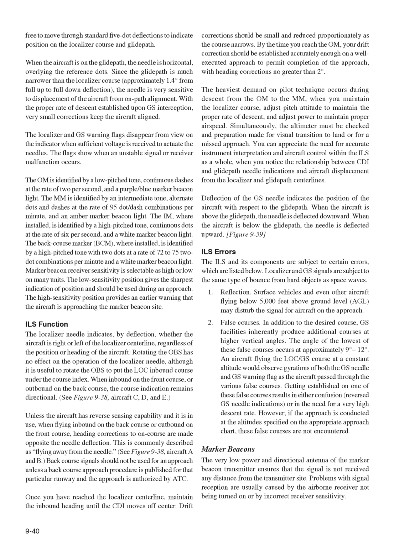The heaviest demand on pilot technique occurs during descent from the OM to the MM, when you maintain the localizer course, adjust pitch attitude to maintain the proper rate of descent, and adjust power to maintain proper airspeed. Simultaneously, the altimeter must be checked and preparation made for visual transition to land or for a missed approach.